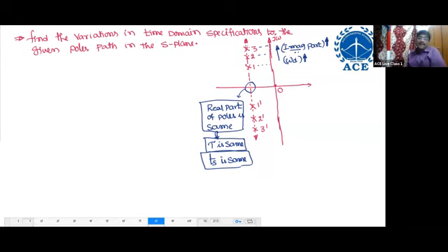What about omega n? The diagonal distance from the origin to the pole, is it increasing or decreasing? That is called omega n. The diagonal distance from the pole to the origin is increasing, so omega n increases. What about theta?